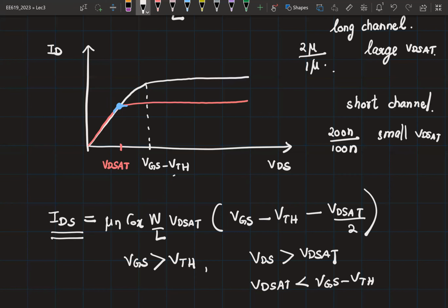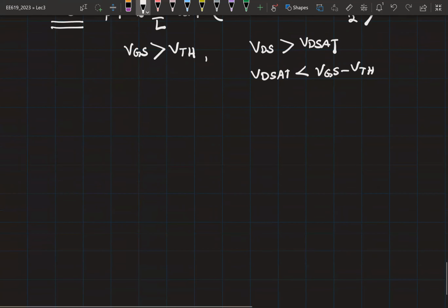So now if you take a transistor, ensuring that it is in cutoff is very easy. You just have to check the VGS. But to check whether it is in linear region, saturation region, which is pinch off saturation, or velocity saturation, is getting slightly complicated, right? So which is why we now have to come up with a unified model to make our lives easier.